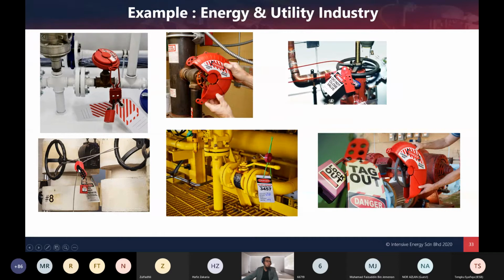Before, people asked, Mizi, is that allowed? I said, allowed, as long as you record. I don't say each valve needs to have 1 LOTO. If 3 valves are close together, 3 LOTO, during a big turnaround or big shutdown, you will use 100 padlocks. So if you can simplify, you simplify. Gather them all. As long as you record it, as long as you put the point, padlock number, tag number, no problem. As long as your document is correct.